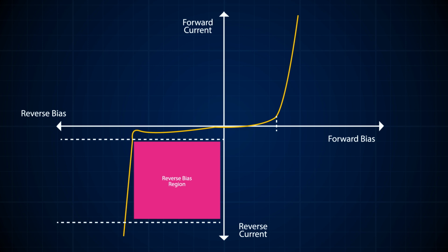The diode stops conducting for a range of voltages and acts as an open circuit. But above a threshold, commonly known as the threshold voltage or the breakdown voltage, the Zener diode begins to conduct. This voltage remains almost constant even with large changes in current, as long as the Zener diode's current remains between the breakdown current and its maximum current rating.